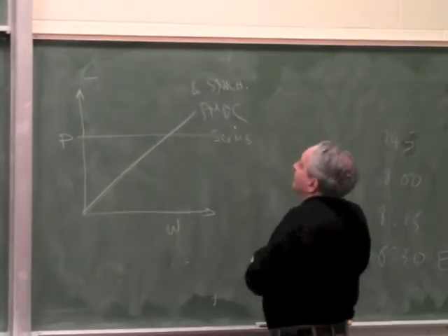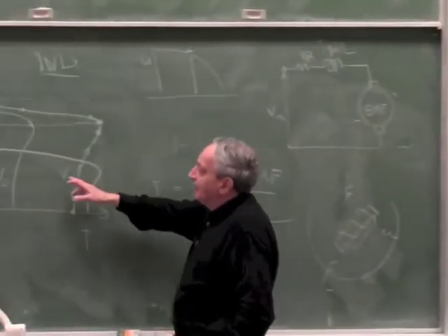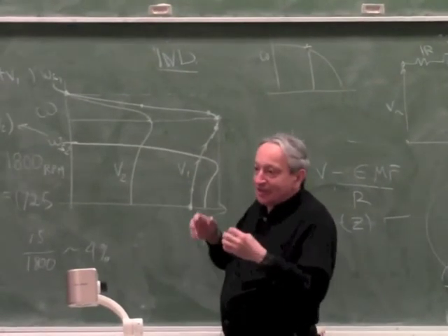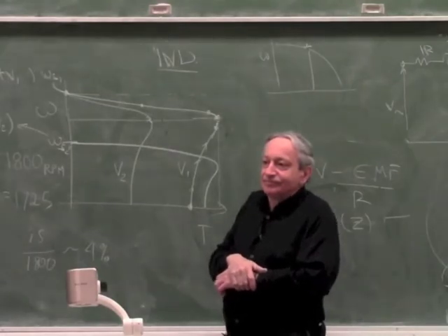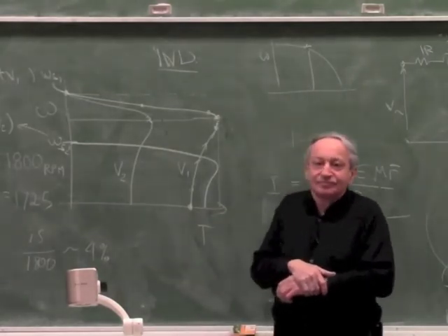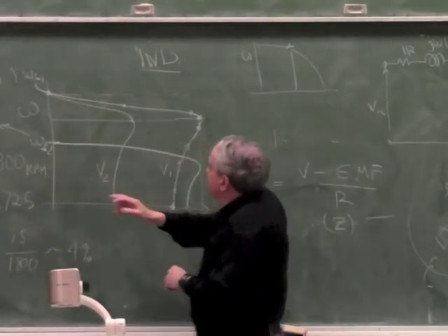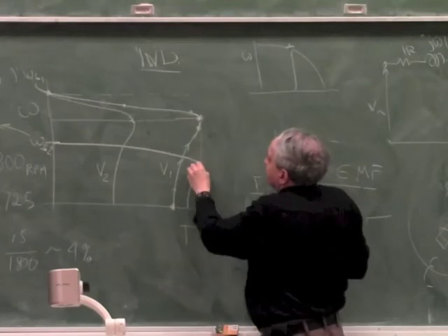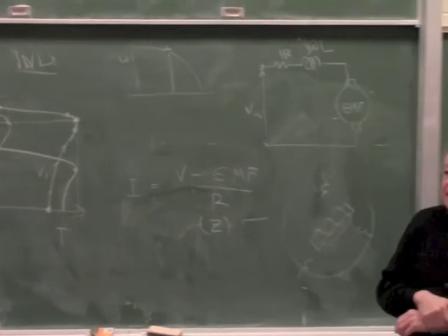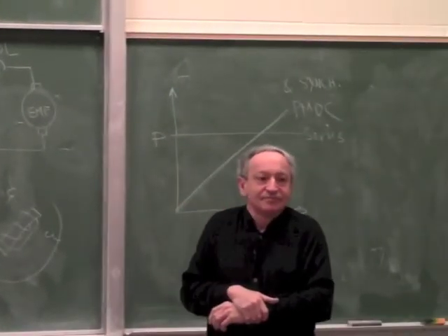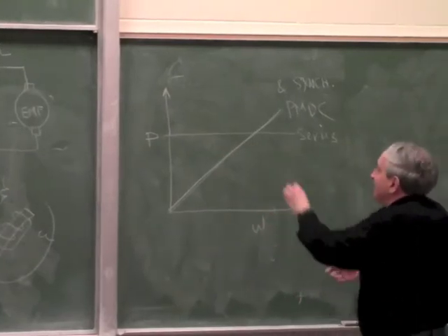synchronous motor. Okay? Now, what will this look like if I play around to keep the current constant? So I change omegas, but I always adjust the current, so this point is the same. The torque is the same, because I'm always working at full current. Okay? Close to linear? Oh yeah, pretty well the same. Basically,